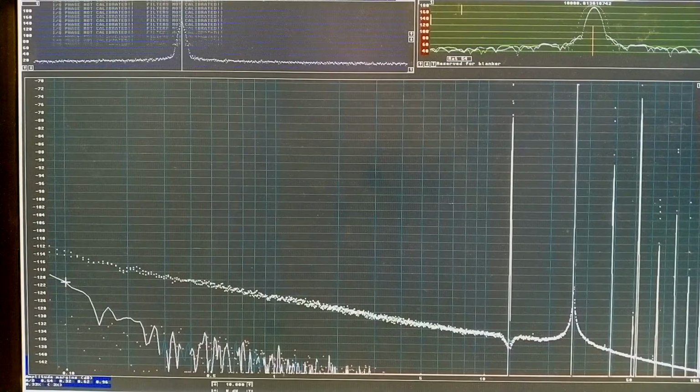So the limiter is okay, and the amplifier does not add amplitude noise modulation. And the conclusion, I think, is that the phase noise I see comes from the crystals. And I had expected much lower, because there are 4 crystals in parallel in this box.